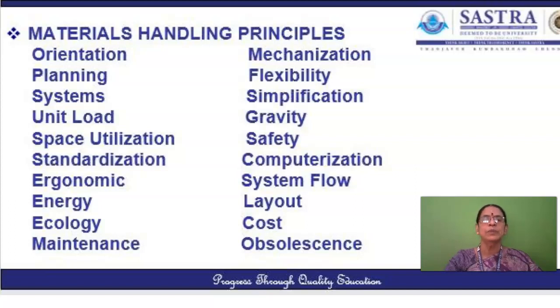The third comes the work principle. Material handling should be minimized without sacrificing the productivity or the level of service required of the operation. The measure of work in the material handling flow, that is the volume or the weight or the count per unit of time, must be multiplied by the distance moved. So the flow of materials into the distance moved will say about the work done by the equipment.